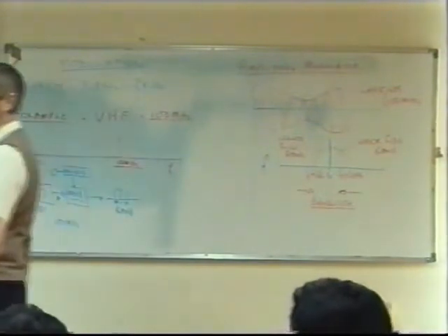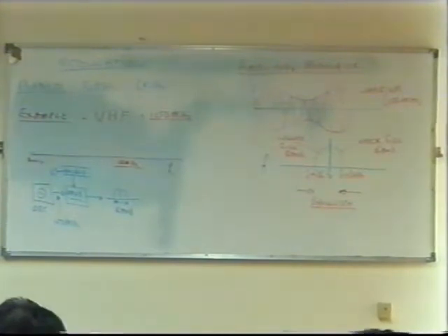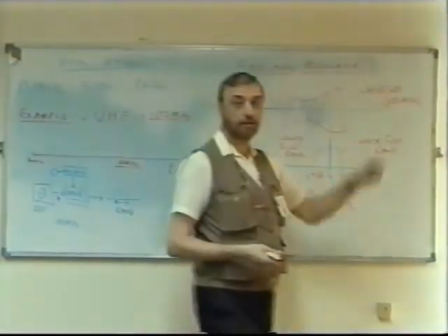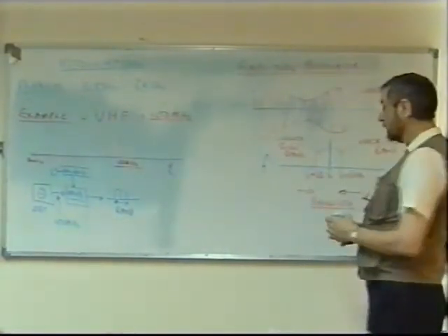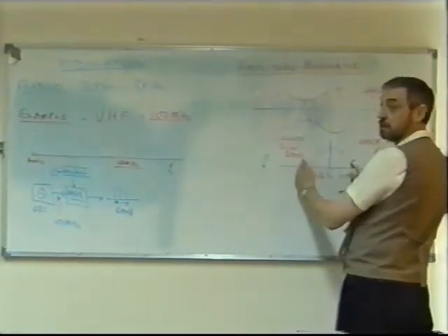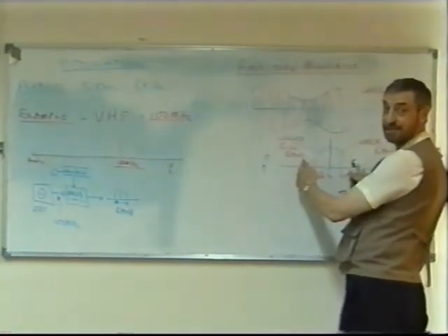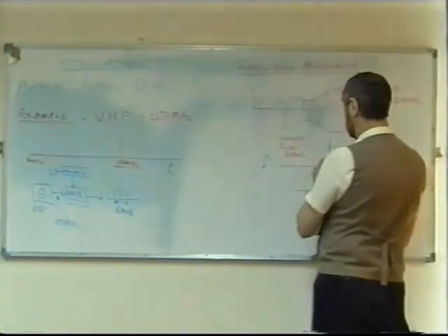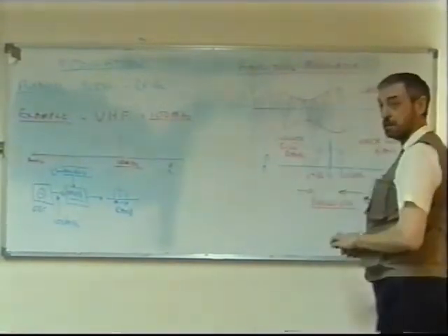If you remember, I mentioned also, since bandwidth is the rate of giving information, I gave you an example of a TV broadcast, didn't I? What did I say was the bandwidth for TV? Very high. Yeah, it's about 5 meg I gave you actually. Does depend, but say 5. Now that's 5 megahertz. If I was going to use this type of modulator to transmit a TV signal, then the bandwidth would be plus and minus 5 megahertz. Yes. 10 megahertz bandwidth. That's very wide, isn't it? Very wide.